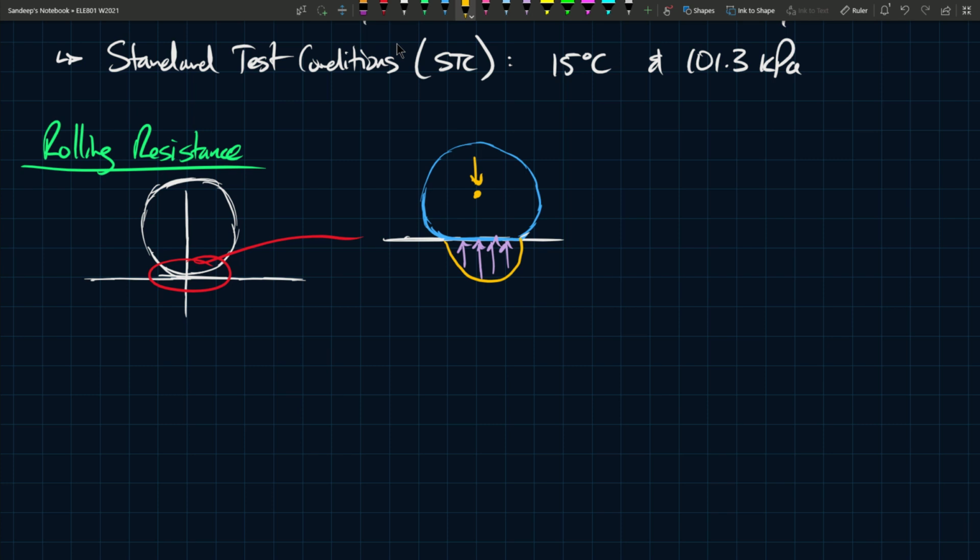So you have rolling resistance, because as the tires roll, as the vehicle moves, the distribution of this force changes. Therefore, you've added some friction to the movement of the vehicle. So, long story short, tires are not perfectly rigid, and that's what causes this. They flatten out here at the bottom, is what you should keep in mind.